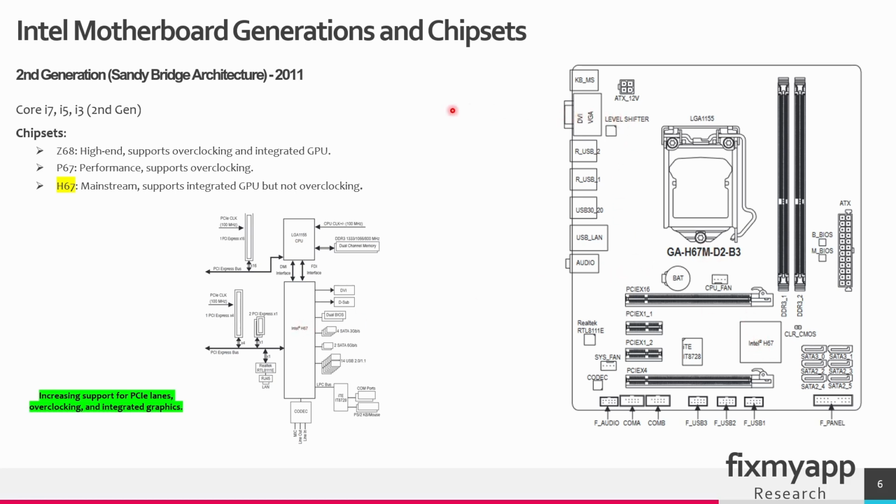go to your monitor. This PCIe slot supports 16 lanes of data, and that is connected to the CPU. So this PCIe slot will communicate with your CPU. Then we have a PCIe slot with 4 data lanes and 2 slots with 1 data lane. So if you look at the mainboard, these are the 2 PCIe slots with 1 data lane, and this is the one with 4 data lanes. And those slots will communicate with the chipset and from there with the CPU.